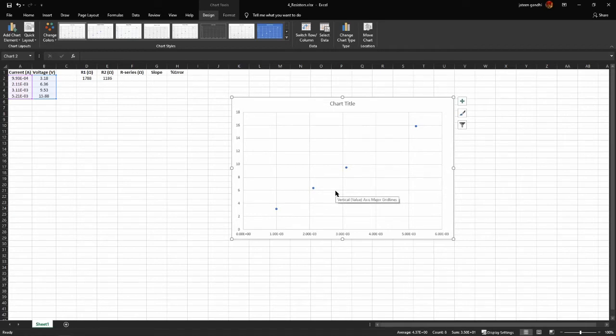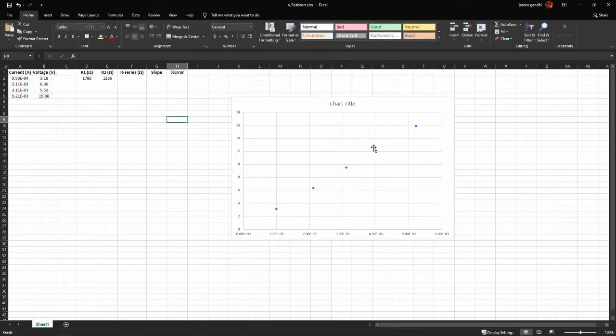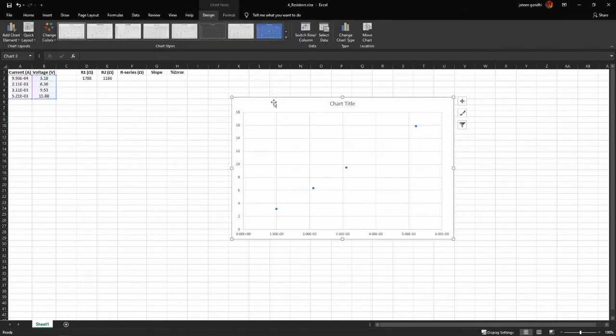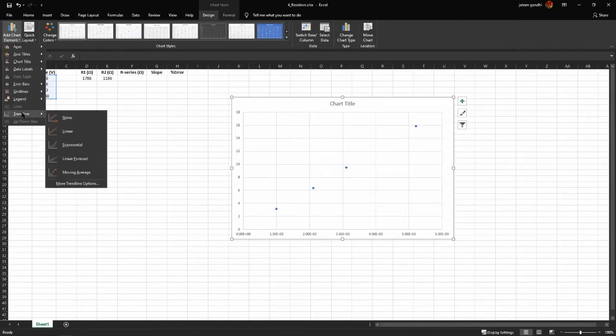Now what we want to do here is add a trend line. That one is in the chart tools option. So for example, if you're outside of the plot, then you don't see the options that you see on the top, there is no chart tools. Those options don't get activated until you select the chart, which now you can see here. And under the design tab on the left here, you're gonna see add chart element. Click, go all the way down, you can see trend line, right?